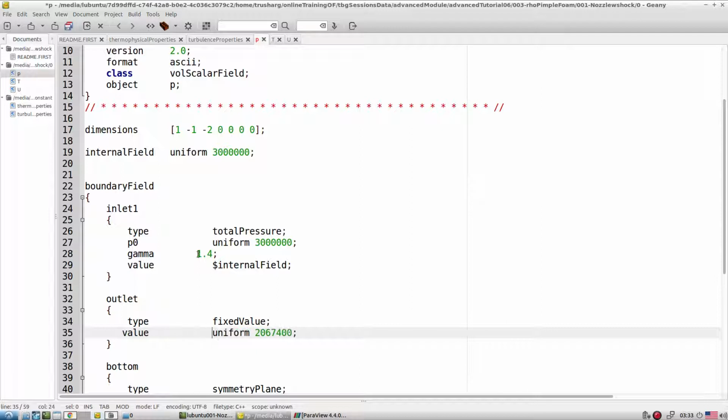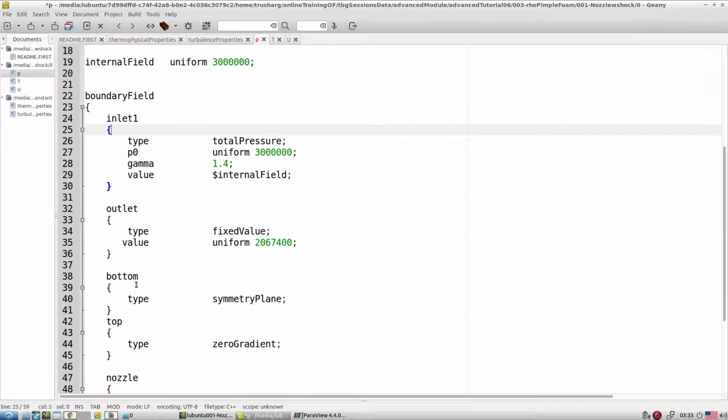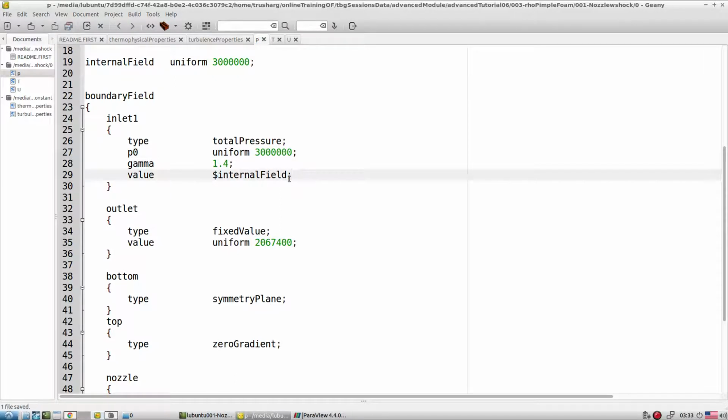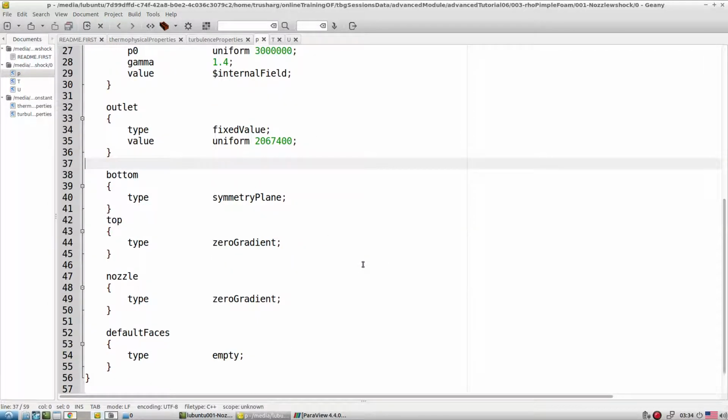Normally, depending on these two pressures, we can trigger the shock. We have to do some back calculations from simple gas dynamics calculations, and one can figure out what the pressure ratio should be that gives you the shock. Not only that, by calculation you can also quantify the Mach number near the shock and the location of the shock. All these things one can quantify based on fundamental compressible flow calculations.